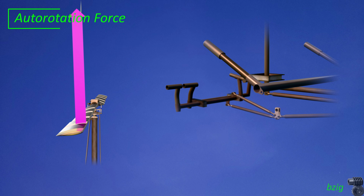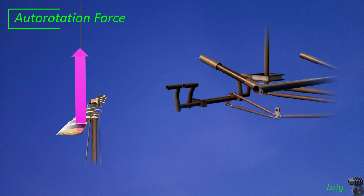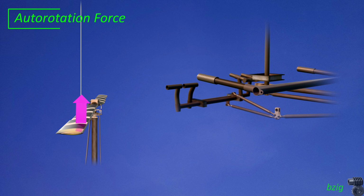The pilot has to lower the collective lever to do this, and this decreases the vertical component of the aerodynamic force, meaning the aircraft will descend, but it allows the rotors to continue turning and producing lift even without engine power.